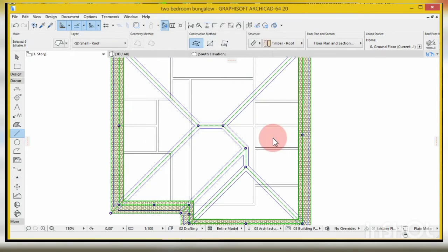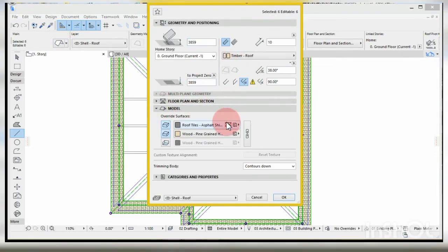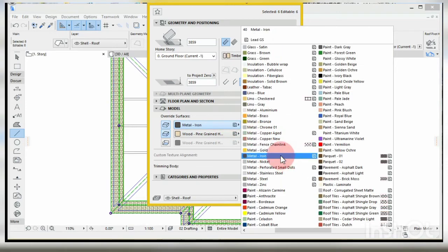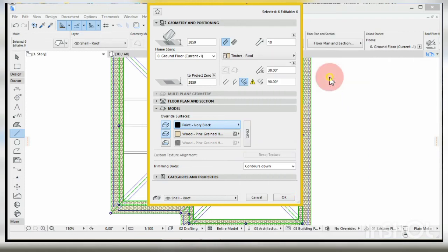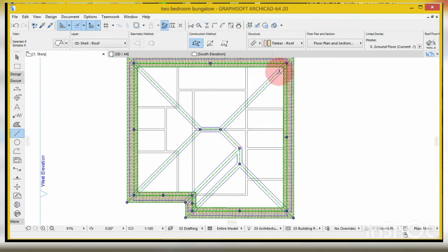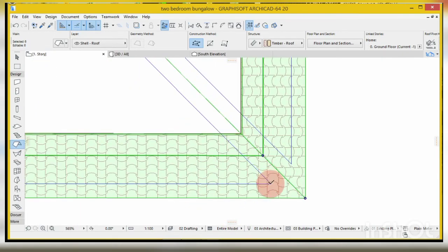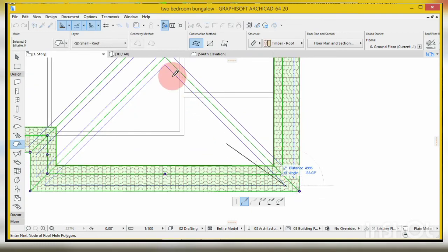So I'll click OK. Let me change the color so you can see the difference at the floor plan. Let me put black. This is it. So remember, as it is selected, you go to your roof, you click on the roof. Don't forget to suspend it so it can allow you to run it. Remember, roof is selected, so you will now run trace with the line. If you don't ungroup it, as you click here, the roof will deselect. So take note of that.